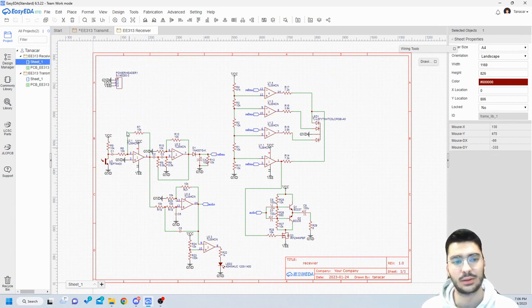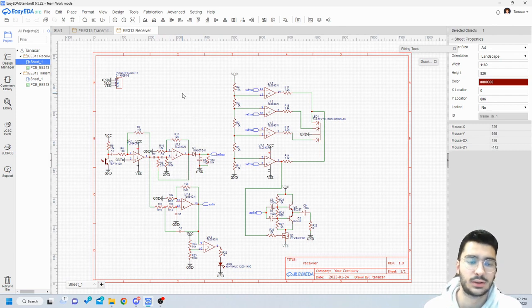First, we get the light signals by a phototransistor, which is biased by a 10K resistor, and we extract the AC signal by a high pass filter. We selected the high pass filter with a 150 Hertz corner frequency, so that we could eliminate 50 and 100 Hertz mains voltage noise. And then we have another second order high pass filter, an active filter design, to eliminate our audio signal. This has a corner frequency of 20 kilohertz, and our reference signal is at 30 kilohertz, so that we assure that they are filtered nicely.